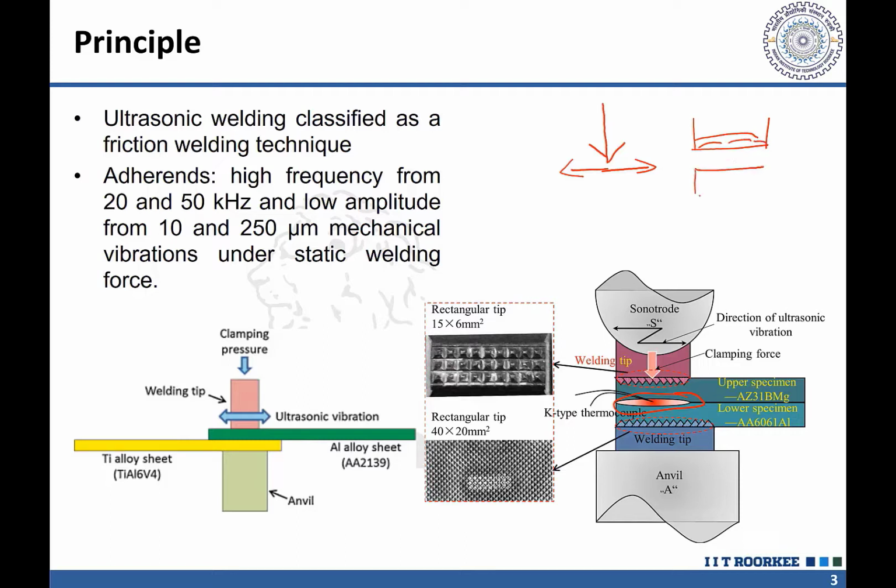Similarly, the surface of the other side is also getting softened, and these are experiencing the shearing movement. Softening, or sometimes localized melting, will lead to the intermixing of the metal from one side to another, like the metal from one side getting mixed with the metal of the other side. That is what we will see more clearly in the next diagram here.